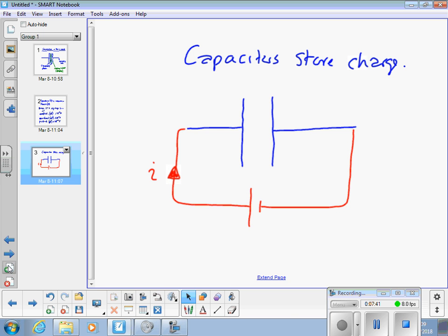If we apply 10 volts here, eventually what will happen is we'll have positive charges attached to this plate, because in electricity current flow is actually electrons going in the other direction. Yeah, but they can't travel through that insulating material of dielectric. So for every positive charge on this plate, because that's the positive end of the battery, negative end being negative, there's negative charge on the other plate. Okay?